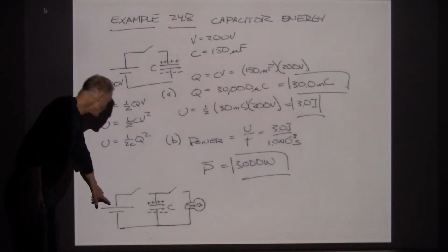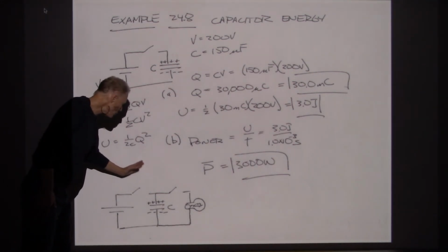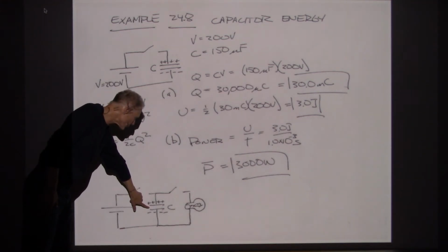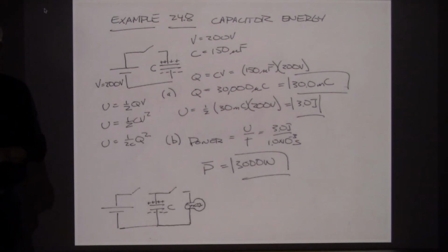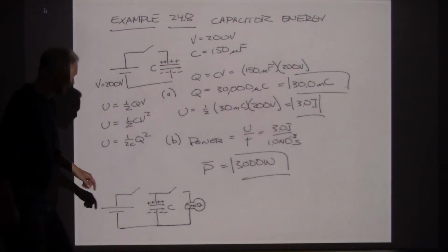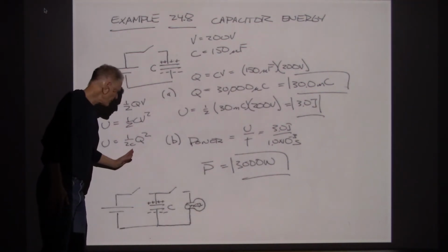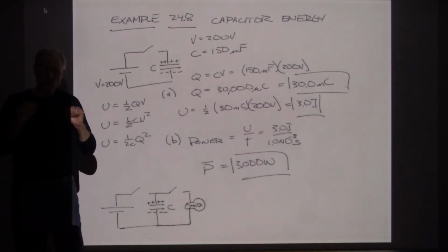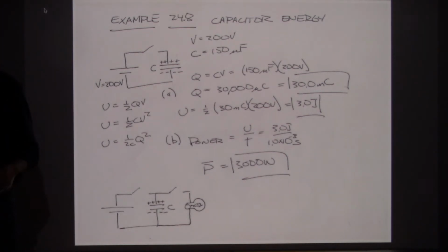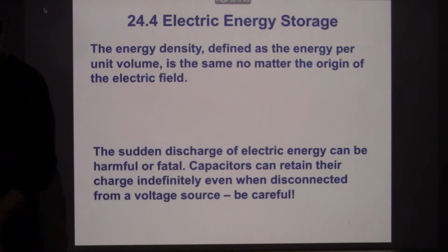So what we've done in the camera is we have a battery, we close the switch to charge up a capacitor. If I'm charging the flash on a camera, maybe I hit something that says prepare flash or something, and so the capacitor charges, and then we open this switch up, and then whenever I hit the shutter, the other switch closes, and all of that energy dumps into the flash very quickly. So that's one of the applications for the capacitors.